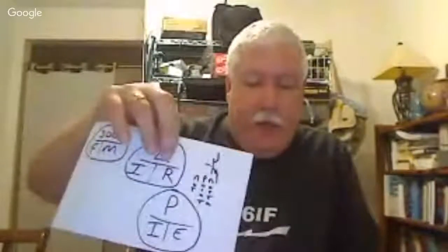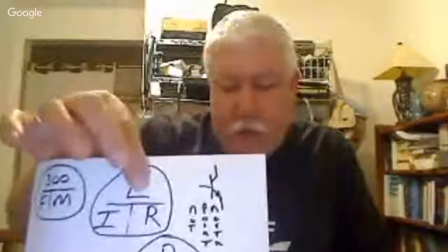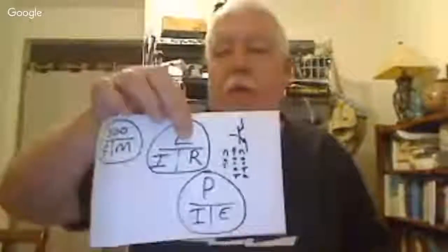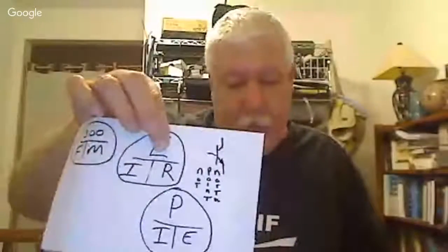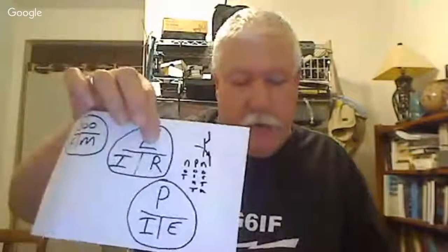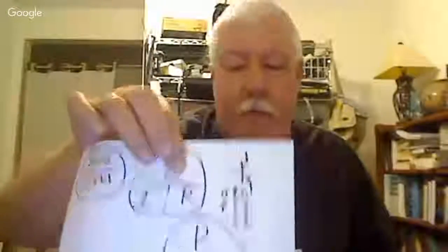All right, D11. What is the voltage across the 10 ohm resistor if the current is 1 amp? Okay, so they gave us a 10 ohm resistor for R, and they gave us 1 for the amps. 1 times 10, I don't think anyone needs to reach for their calculator. 1 times 10 is 10. Okay? And it's in volts because they asked for the voltage. Be careful to select the right 10. There may be another 10 in there that might be some other suffix. Just make sure you get the right 10.